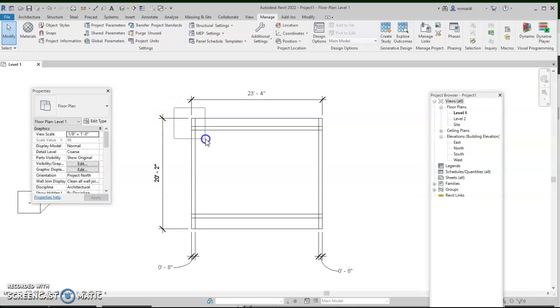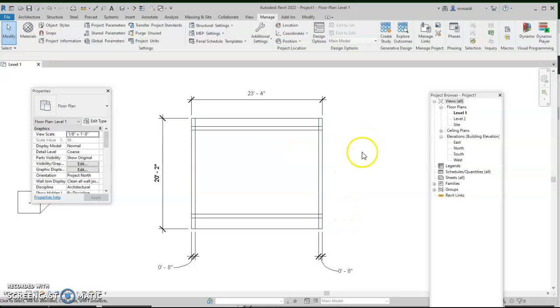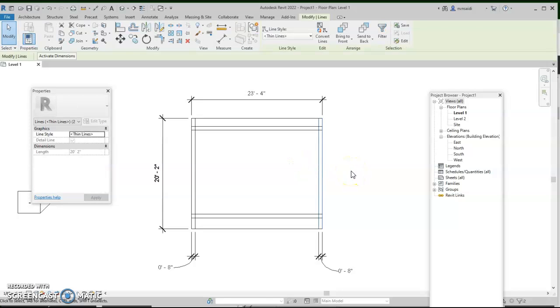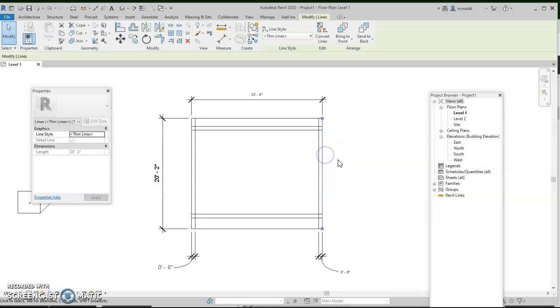What does it mean? I drag downward with my cursor, pressing on my mouse, and it picks up everything that's within its lines. That's picking everything. I'm going to hit Escape. If I go this way, I'm dragging upward. I see the rectangle in a dashed line. Anything it touches, it picks. I can also pick one item at a time. I call it picking fork.